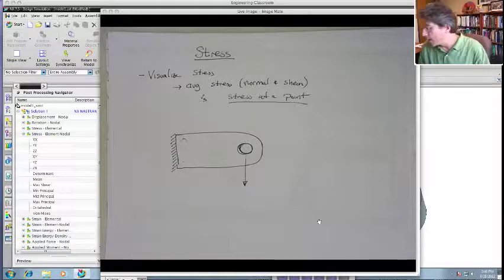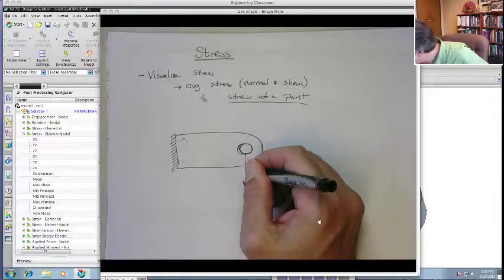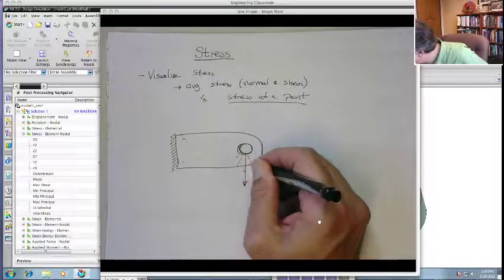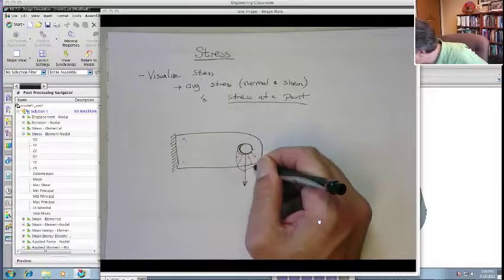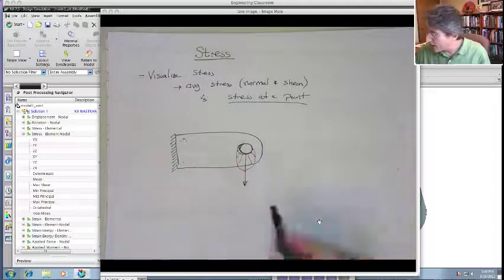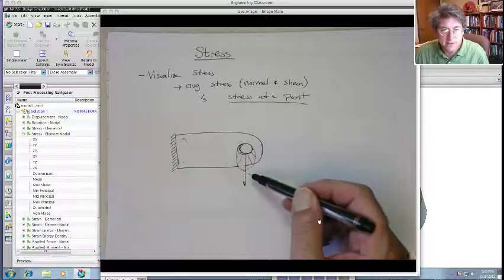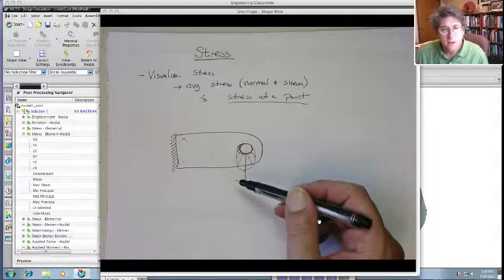I'm going to assume that this has a radial distribution. This is something you can do with finite elements, a more detailed bearing type of load. You can see it's maximal at this point. It acts in the radial direction. It's actually a sinusoidal type of distribution.